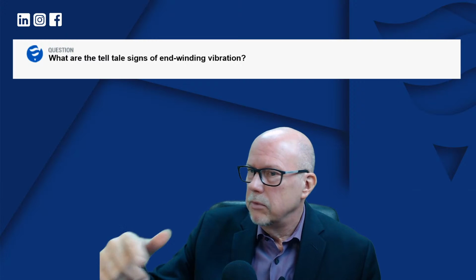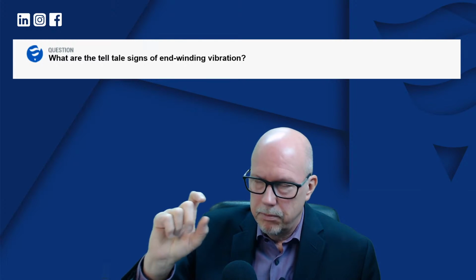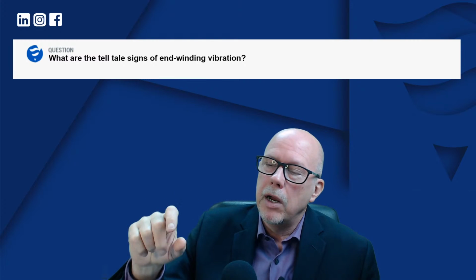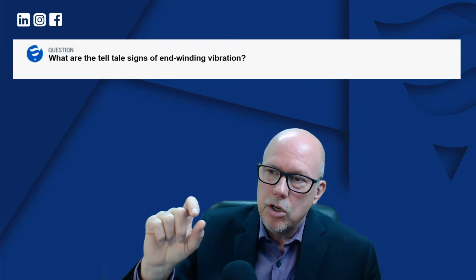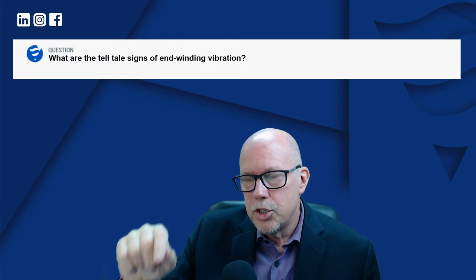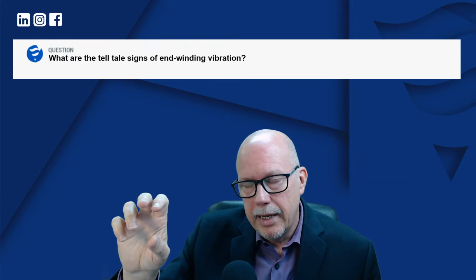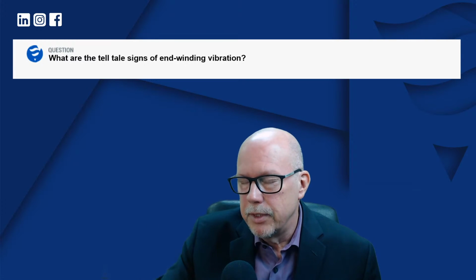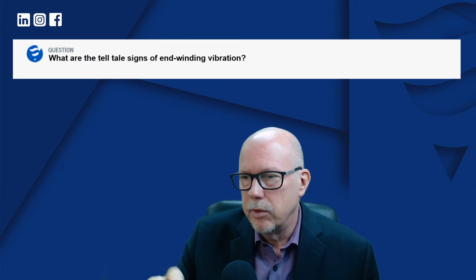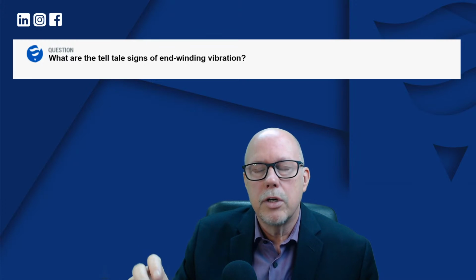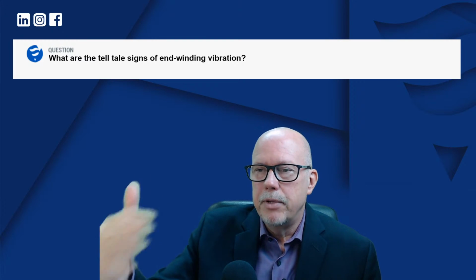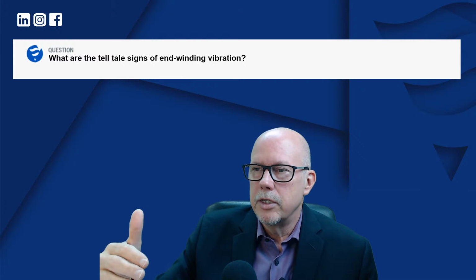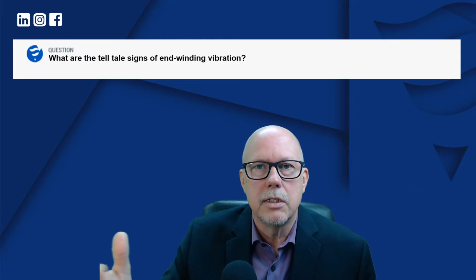And some people say, well, we thought that was partial discharge. Well, partial discharge will create, in some instances, some powder, but you will see that the powder is caused by discharge between the insulation and a grounded piece of material or another insulated piece of material. You don't see partial discharge between the insulation and a piece of FR4, or between insulation and a wet tie. That doesn't exist. There's no reason for that.